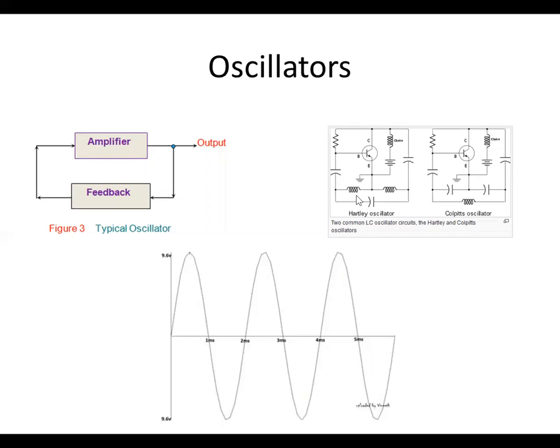You can't generate an oscillating signal with just passive components, because what the active components, whether it's the transistor or the op amp, are doing is making sure that sufficient energy is brought back into the system, because you do have resistive losses in these passive reactive devices.